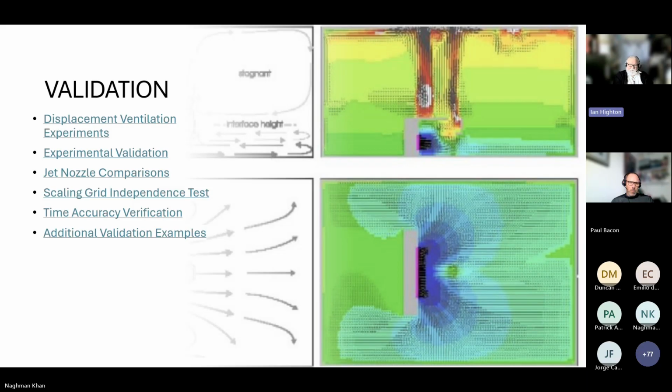Scaling and grid independence. This is a classic problem for other CFD packages. If you change the grid or change its density, you quite often get very different results. So that's a series of tests on a small cube, which is basically three different mesh densities, exactly the same physical size, but very different model sizes. And the agreement again is nice. So that's very good.